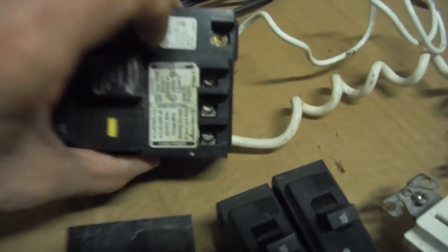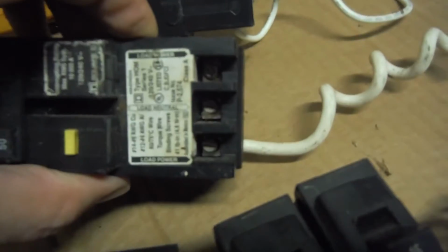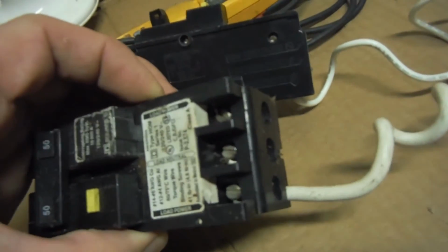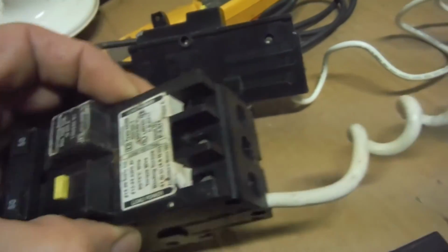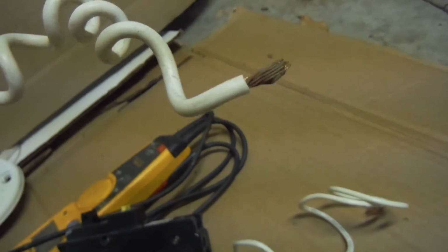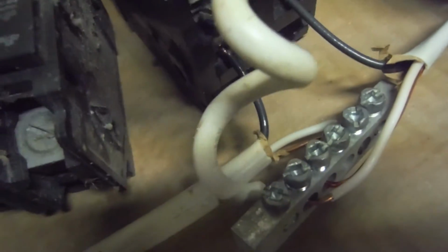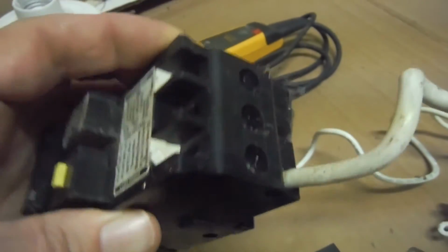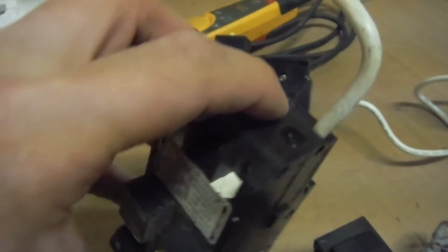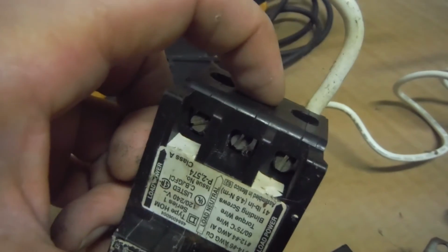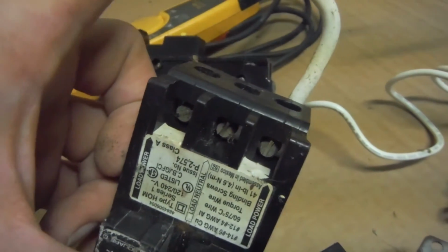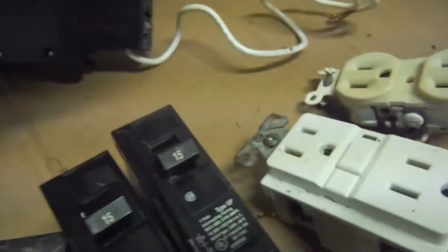The only difference with these guys, as you can see right here, is you'll be running a common line as well as your ground and your two hots for a 220. So this little curly Q piggly tail right here would plug in right there on your common bar on the breaker panel, and your common from the wire would go, I believe it's this middle one right here. Yep. It would come right here on your middle one, and then it would be hot and hot right here. Your ground would just go to the ground bar.